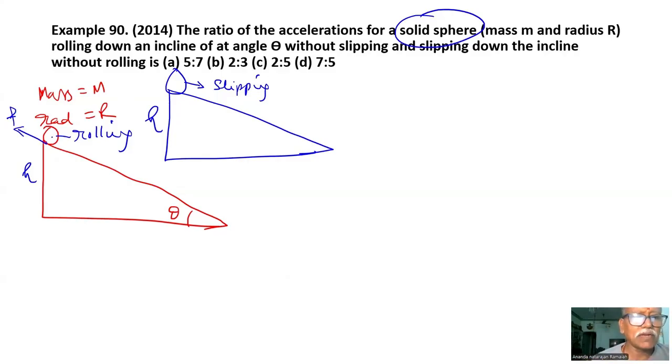Therefore, this will develop a torque of Fr. Its radius is R. Fr is the torque developed by this resistance. That's why it will roll. If the resistance is sufficient to rotate this, to roll this, there won't be any slip. That's why in some sums they will say zero slip. If resistance is not sufficient, then it will do both rolling and slipping. That type of sum they won't give. Either they will give slipping or they will give rolling.